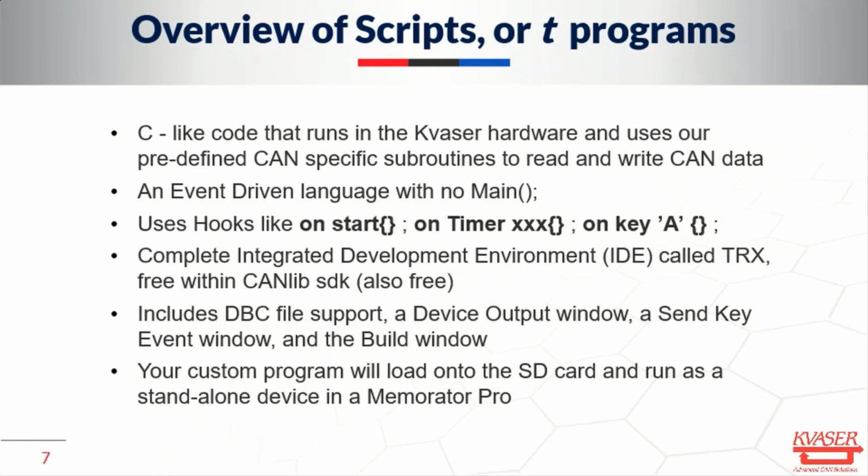It allows you to have a C-like code that actually gets downloaded and flashed onto the Kvaser hardware that executes when powered from the CAN bus, and it's an event-driven language that allows you full control of the logging process and allows you to totally interact with the bus as well as log, so you can simulate a failing device and log the conditions that the ECU goes into to handle that failing device or handle that actual log condition.